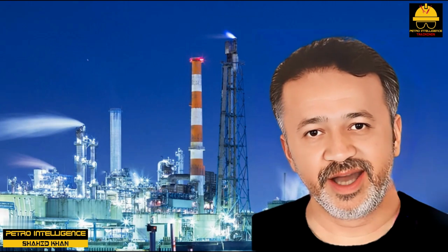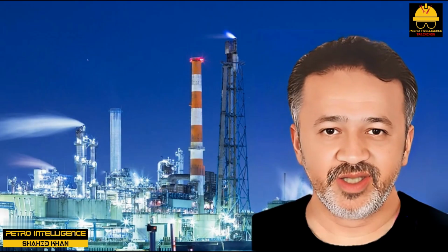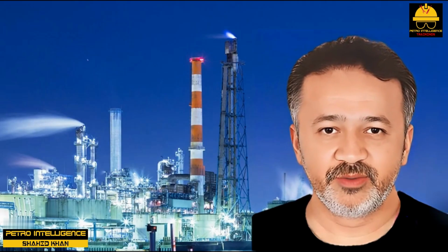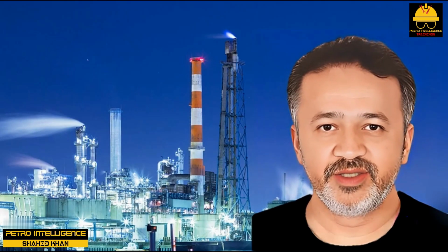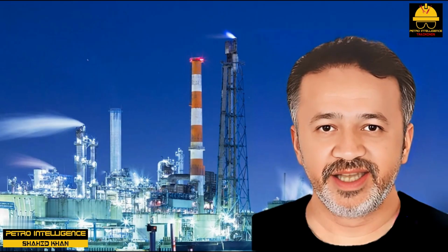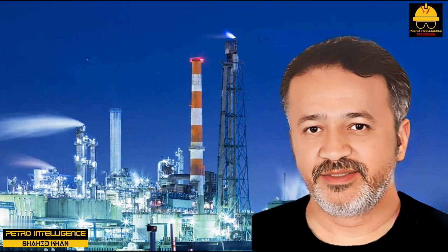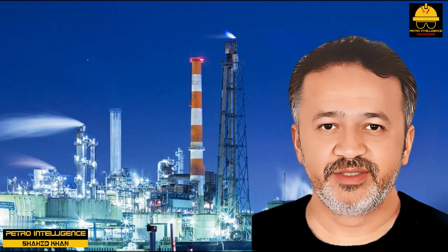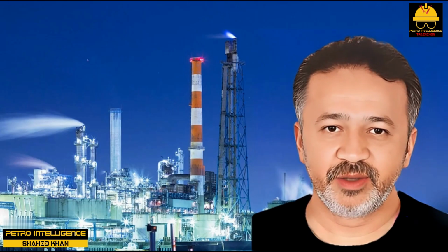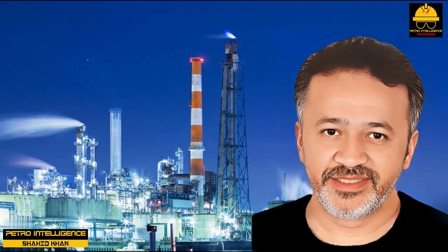This required several hours. As the suction pressure rose due to the more volatile refrigerant, the operators increased the refrigerant compressor speed, and hence the refrigerant circulation rate. Eventually, using this and other tricks, he increased unit capacity to 25,000 BSD.